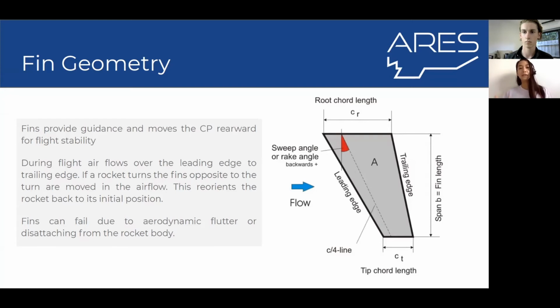And the second thing that's important to consider is the method of how it's attached, because if the fin was to fall out during flight due to the high forces of airflow, then you're in a bit of trouble. But ideally we'd want a minimum of around 3 fins. That's convention wise. I feel like 2 would be very useless, but 3 provides you with that minimum stability.